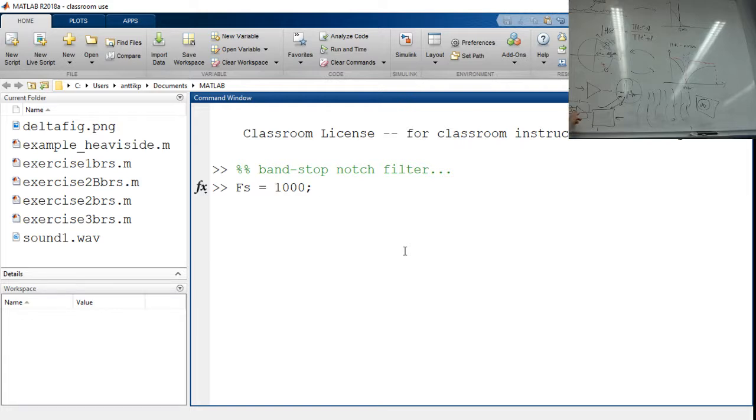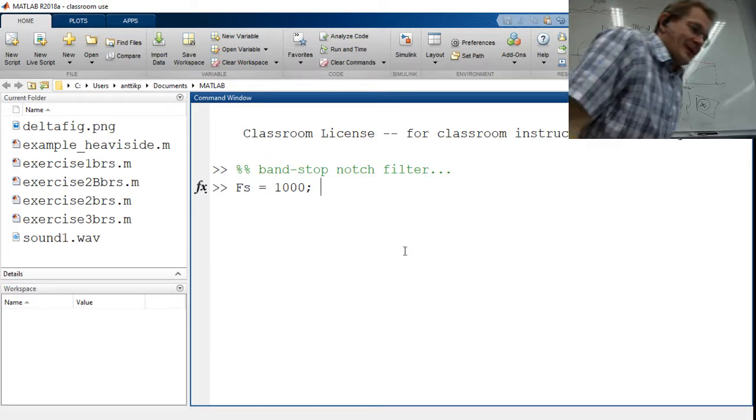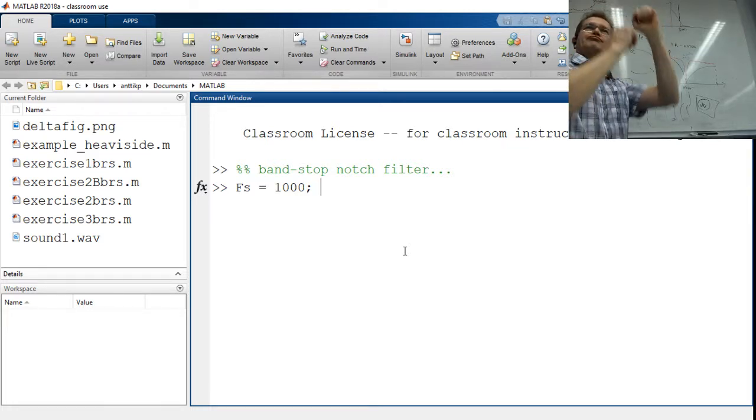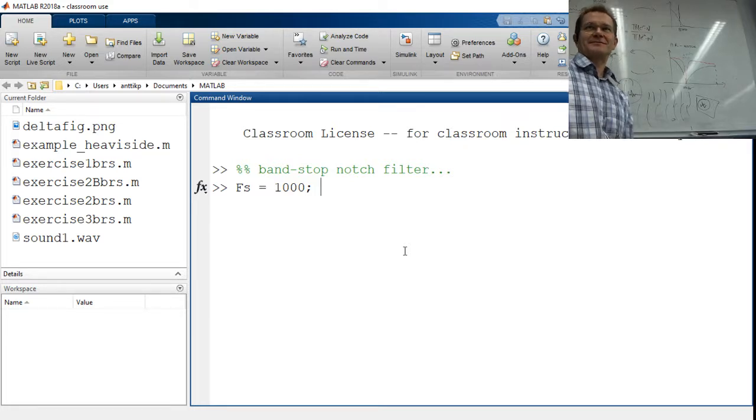space, and if you have, say, 8th order, you have already 16 passive components plus 4 operational amplifiers. That takes that much space. What? 1 square centimeter, at least. Okay, the same in software takes this much code, not more than that. It still fits on 1 page if you do it smart.